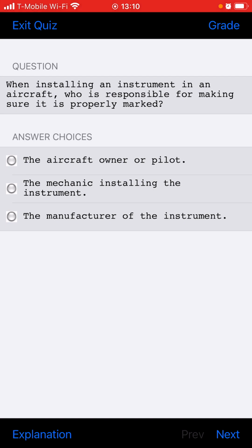What systems are commonly used to activate the landing gear warning system? The throttles, the thrust lever, and the wing flaps. A throttle or the wing flaps. Instead of the throttles, you can say thrust levers.